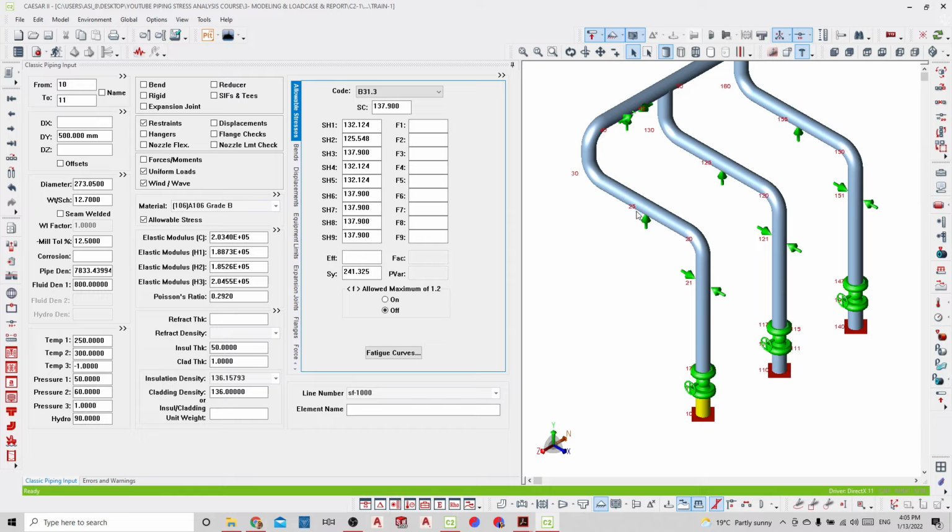When the support is not in action, it's named a non-linear support in Caesar. The non-linear support is the support which does not have load acting on it. In this case, the stiffness of this support will be removed from the stiffness matrix in the calculation.